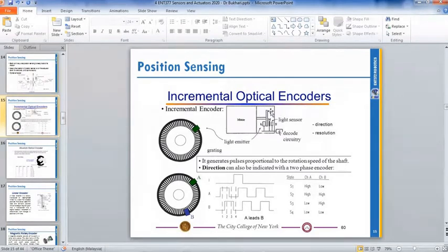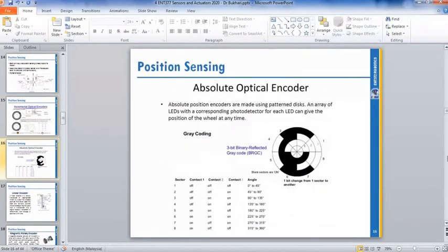If you purchase a DC motor, whether you want to use an encoder or not, because the price is almost similar, better you purchase one with an encoder, because now they put a magnetic encoder at the back of the DC motor, and the price is quite similar, maybe a little bit higher. Better you buy the motor with the encoder, because when you use a DC motor you need to measure your position. Without an encoder it is not accurate.